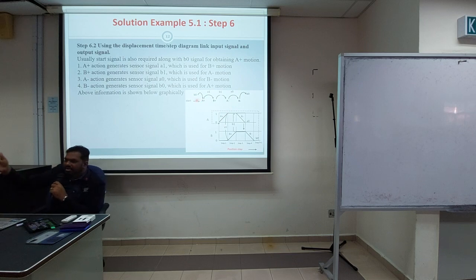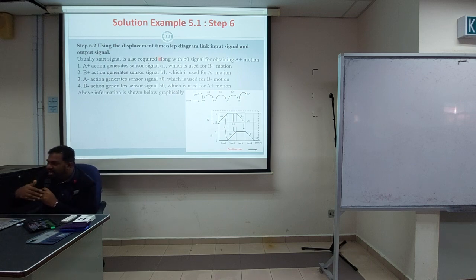So apa yang akan activate the cylinders? So kalau B0, so here if you cylinder A nak extend, so B0 must be on, baru cylinder A akan extend. Cylinder A extend, A1 will be on. So dia macam akan ada sequence, so one after one. So yang ni you kena letak lah. So if you don't put this, so you don't know which one will activate which one. Okay, so maybe yang slide ni is not prepared by myself, so it's by Encik Syaril yang ajar sebelum ni.